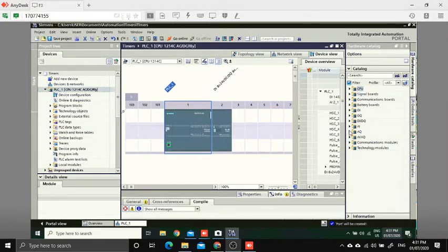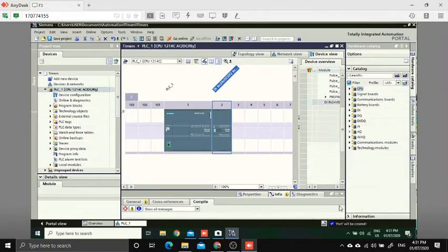As you would notice, it already detects our PLC in the particular laboratory and its slot. Before we proceed to the programming, let us first configure the expansion module, since the expansion module has a default input-output address. Now, in setting the input-output address,